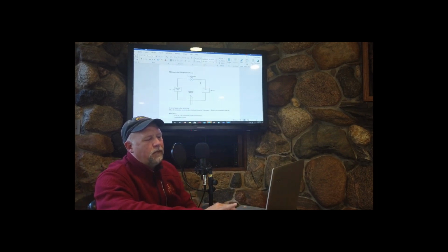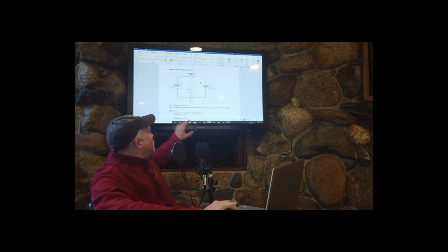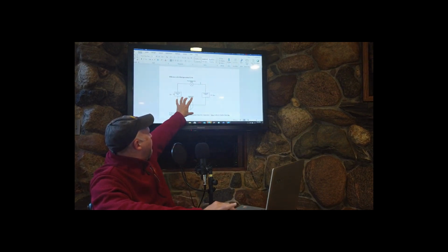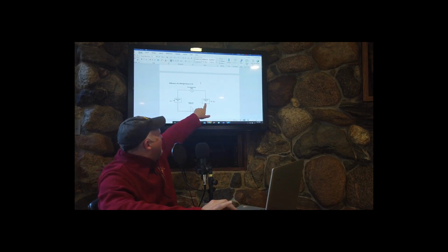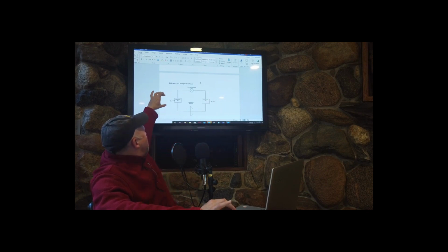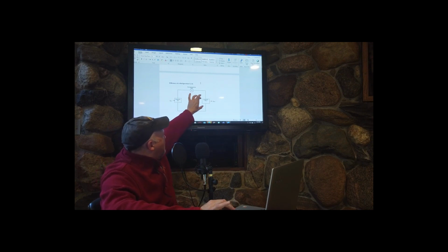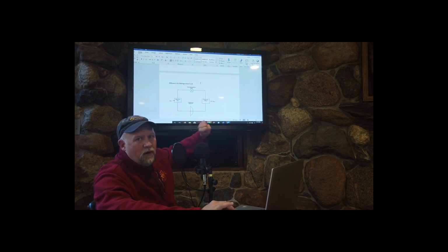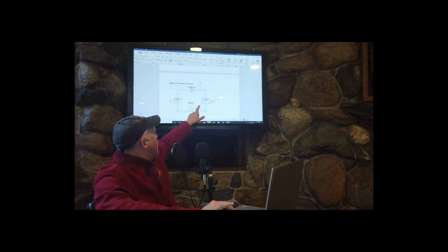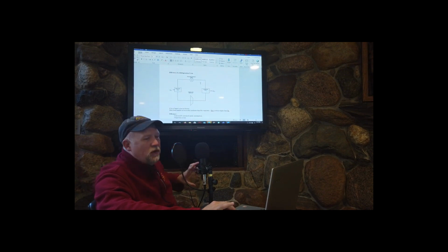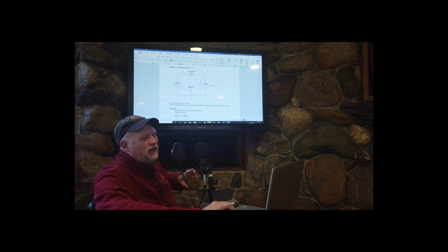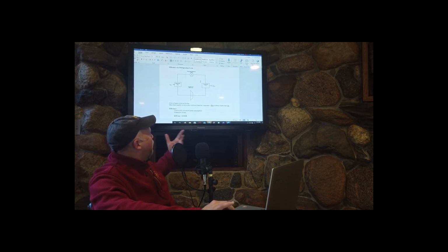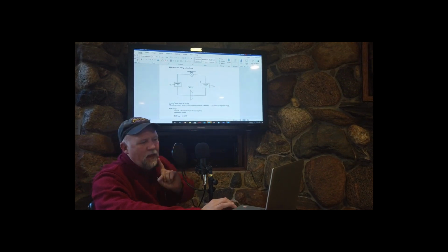All right. So here's that efficiency of the refrigeration cycle. Remember, on the heat pump, this Q out at the condenser is actually being rejected into the house. We are rejecting our heat. The energy that we pulled in from the ground plus the energy at the compressor all goes out at the condenser, which is in the room for a heat pump system that's running in heating mode. So a coefficient of performance is very different than an energy efficiency, just like a thermal efficiency as a percentage. Be cautious here.